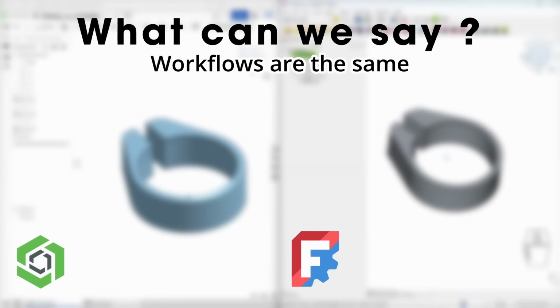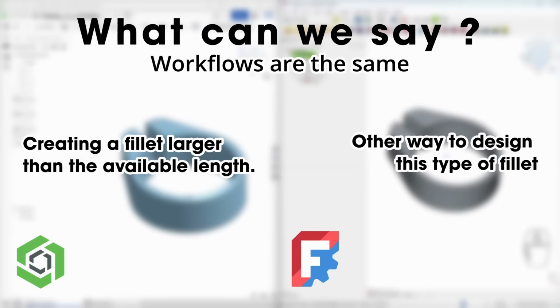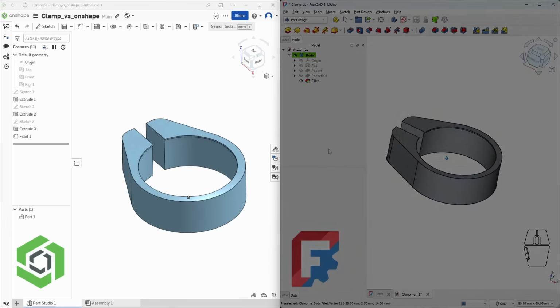For this fillet operation, we can note that once again, the workflow is the same. It's not easier in either case. The biggest difference lies in the flexibility to create radii larger than the available length with Onshape. In FreeCAD, this operation is not possible and requires finding a workaround or another way of modeling to achieve the desired shape. Let's now focus on creating custom planes, starting with Onshape.